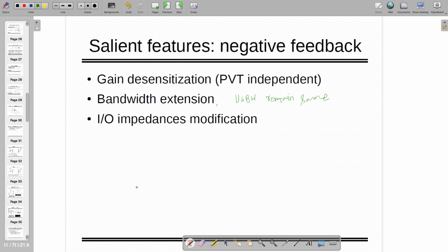As we know, if it is a voltage controlled voltage source, we want Rin to be infinity and Rout to be as low as 0, right? This is what we want. But these numbers will actually have some finite values. They cannot be infinity or 0; they will be in kilo ohm, mega ohm, or here might be 50 ohm or something. So if it is kept in negative feedback, what is going to happen? Will it destroy this characteristic, or will it improve it? Let's see that.